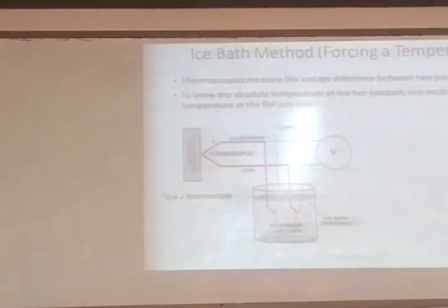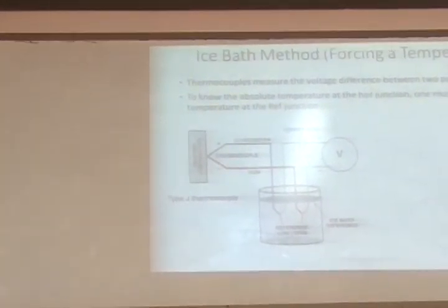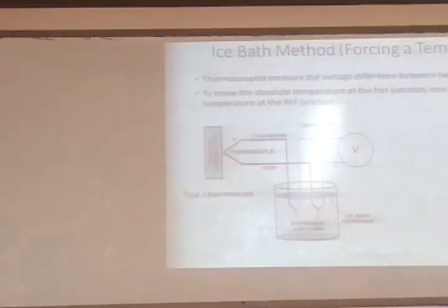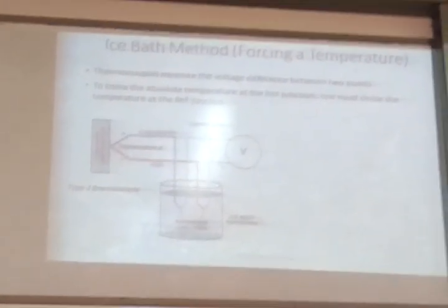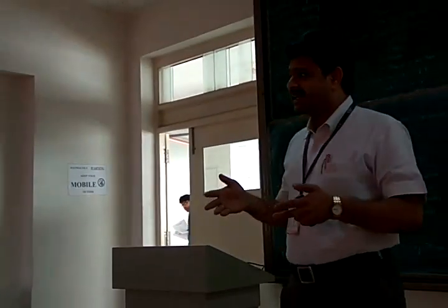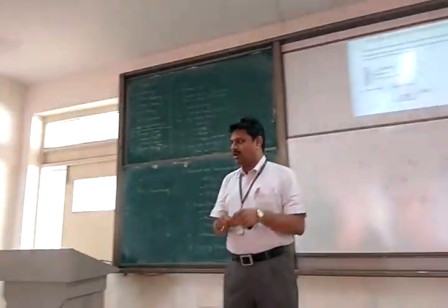You simply keep the thermocouple near that, connect it to an oscilloscope, and you will see this small noise component come. If you enlarge it, it will be a 50 hertz signal from the AC line that interferes with the voltage developed in the thermocouple. You will be able to see it. So you want to know whether it is actually noise or the signal coming from the thermocouple.